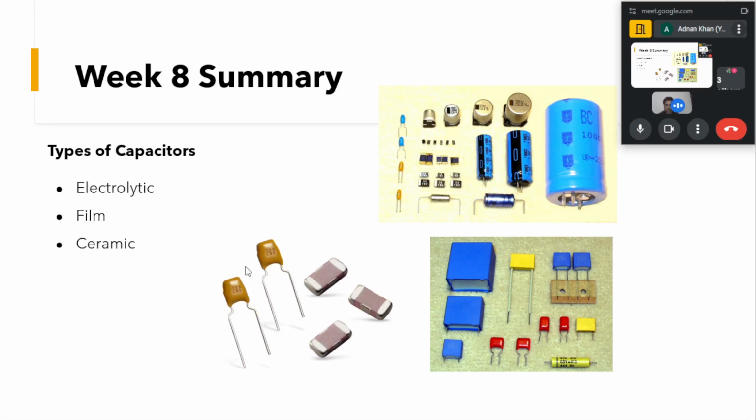to the PCB. And the picture over which there is the cursor shows ceramic capacitors, and they can be of the SMD type or the through hole type. SMD are surface mount devices, which are mounted on the surface and soldered to the surface of the PCB. And with through hole, the leads of these capacitors go through the holes, and then we solder them at their respective places.